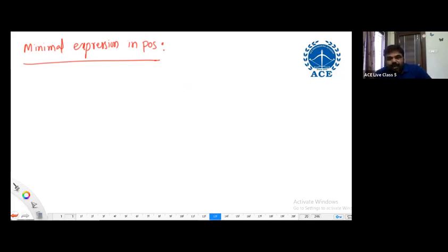For that, grouping is similar to SOP. Elimination of variables is similar to SOP. Considering variables which are not changing in a grouping, we write the sum term. The difference is 0 is uncomplemented, 1 is complemented. Right. For that, let me take one example to get more clarity.